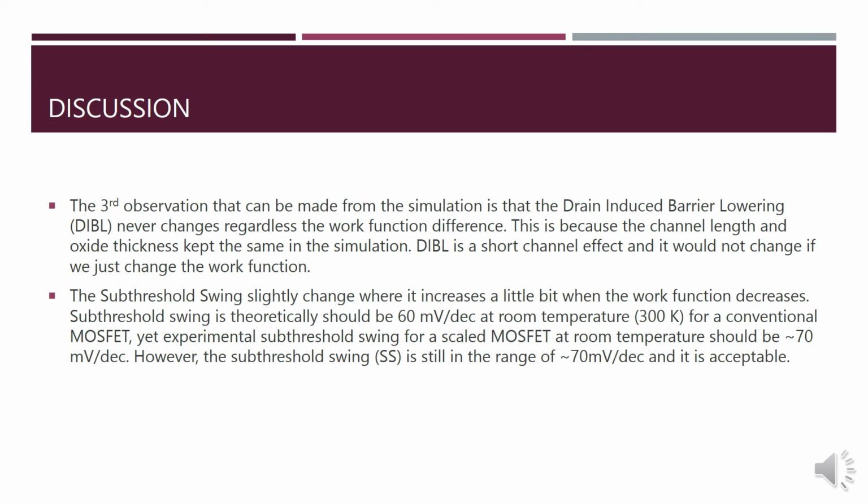The third observation that can be made from the simulation is that the drain-induced barrier lowering, DIBL, never changes regardless of the work function difference. This is because the channel length and oxide thickness were kept the same in the simulation. DIBL is a short channel effect and it would not change if we just change the work function.